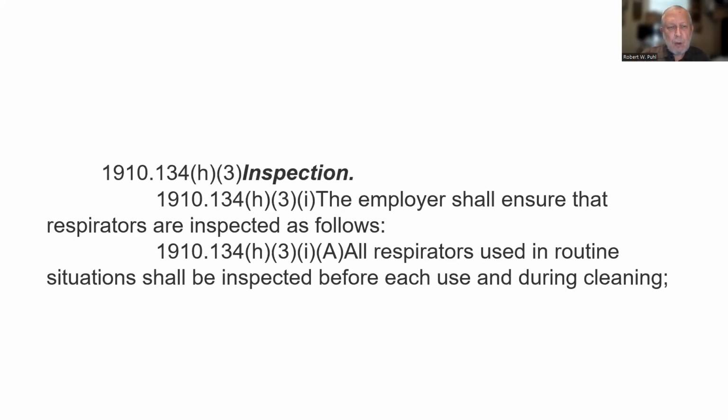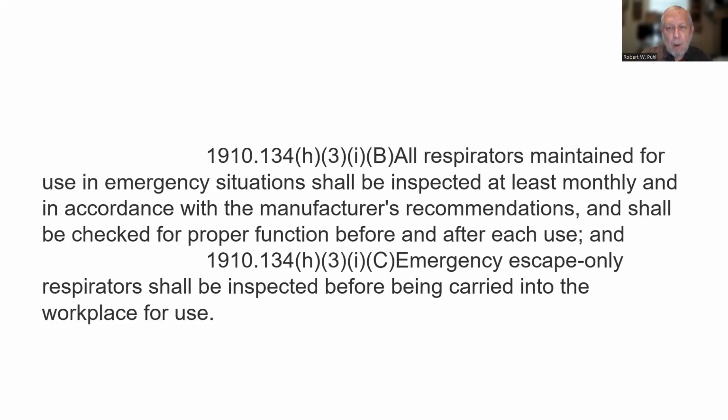Inspection. The employer shall ensure that respirators are inspected as follows. All respirators used in routine situations shall be inspected before each use and during cleaning. Routine situations, okay. All respirators maintained for use in emergency situations shall be inspected at least monthly and in accordance with the manufacturer's recommendations, and shall be checked for proper function before and after each use. And emergency escape-only respirators shall be inspected before being carried into the workplace for use.